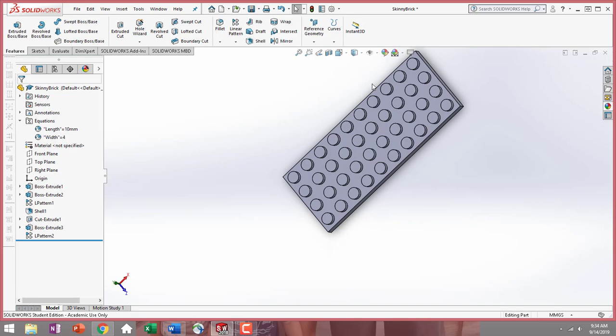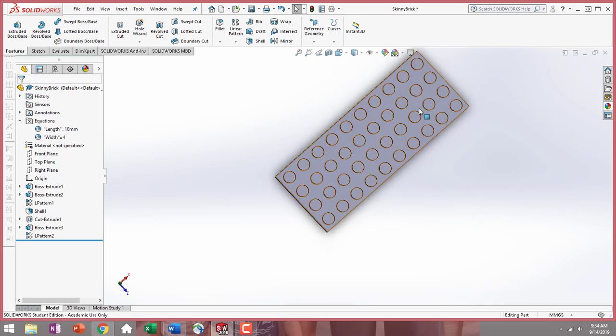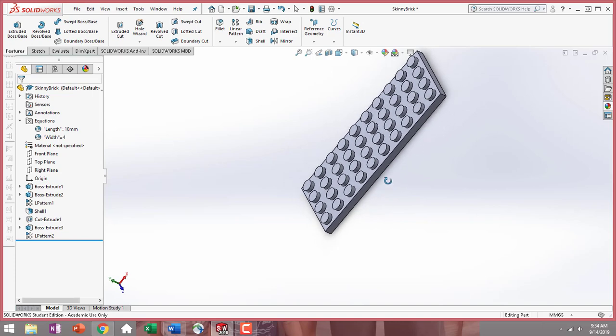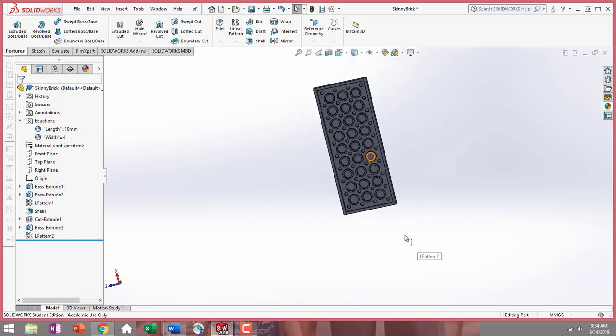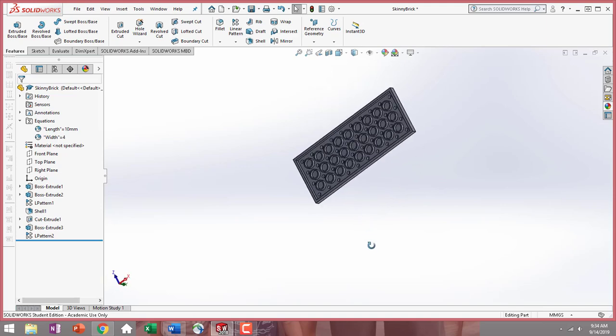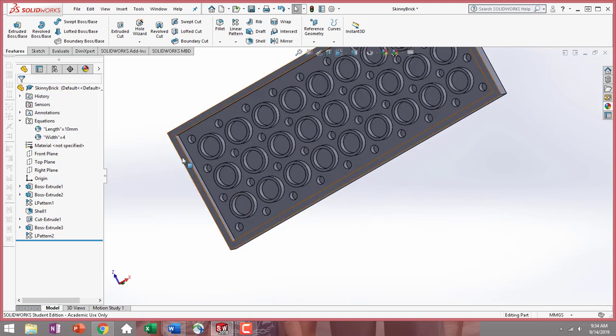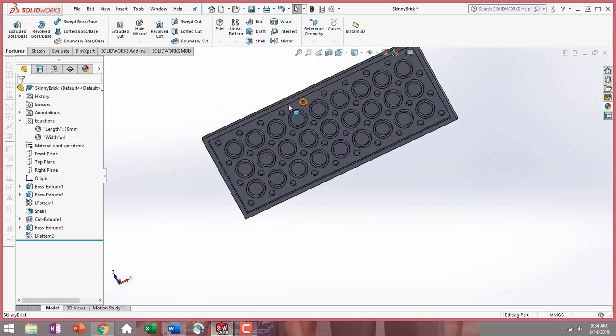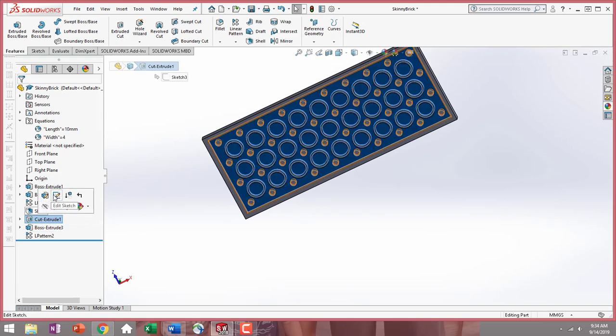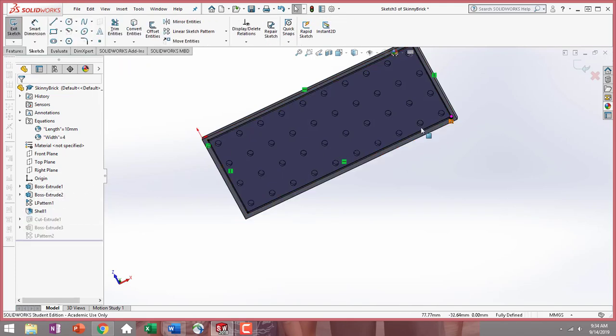If you have no errors pop up, and your Lego piece now has gotten way larger, but your knobs are still covering the whole top of your piece, go ahead, roll it onto the back. Make sure those underneath circular annuluses are covering the entire piece as well. That extrude cut you had to make inside your shell face has gone the whole width. If you did not connect to your edges, then your extrude cut will only remain in one area. So you'll need to go back into that extrude cut, edit that sketch, and make sure you stay connected to those features.